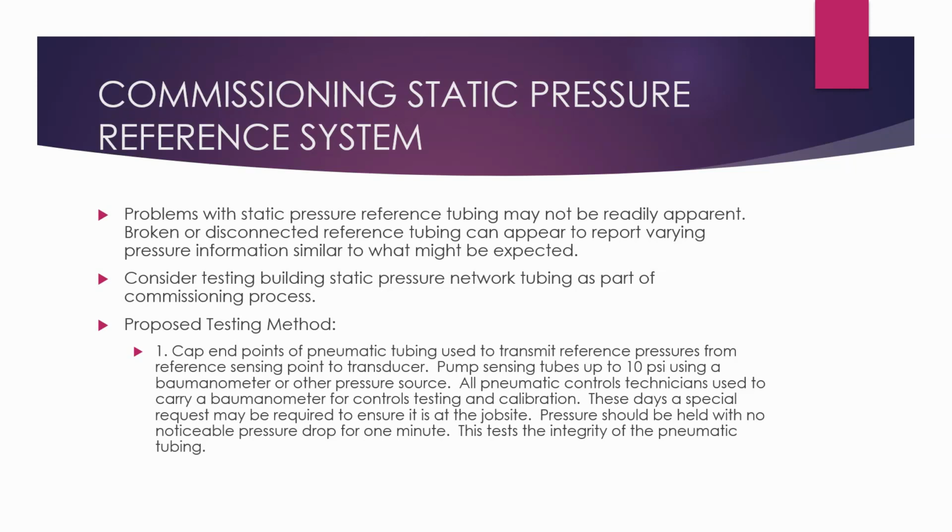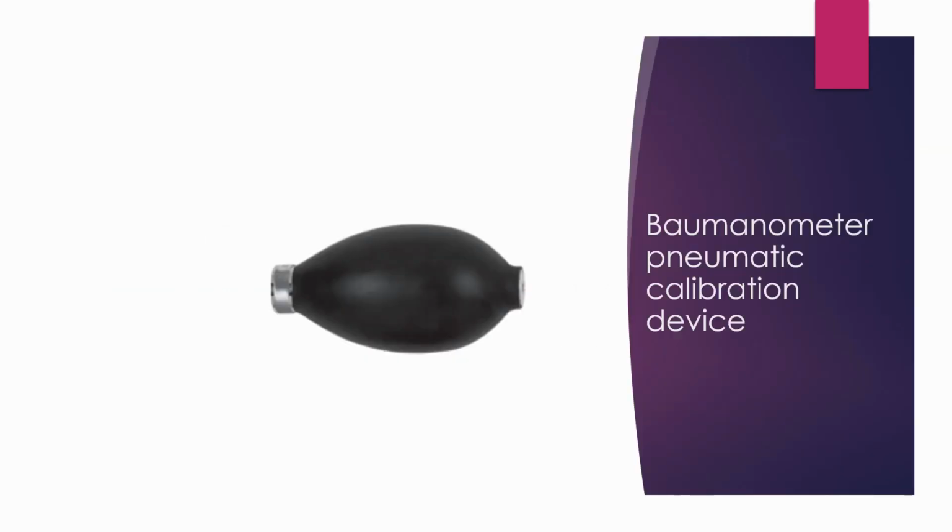So you pump it up, make sure that there's no holes in your tubing, and because you saw these plugs being installed, you know where the ends of the pressure is being sensed, and then you just make sure that the pressure is held at that 10 psi for some length of time, probably just a few minutes, because there's essentially no volume in this tubing. So that's a picture of the thermometer.